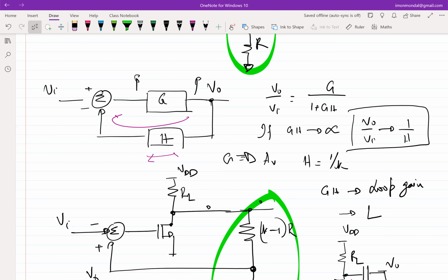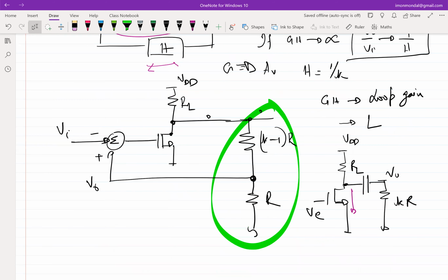So it doesn't matter what you put, the voltages, whatever they were supposed to be in the absence of any of those blocks, remain the same. H can be 1, 2, 100, 0, doesn't matter. V0 is always V times G. That's what a block diagram means, which means in circuit parlance, you are assuming they are voltage controlled voltage sources. But in this case, you see that it's not a voltage controlled voltage source. Depending upon how you change H, the forward transfer function will change because they are not unrelated.